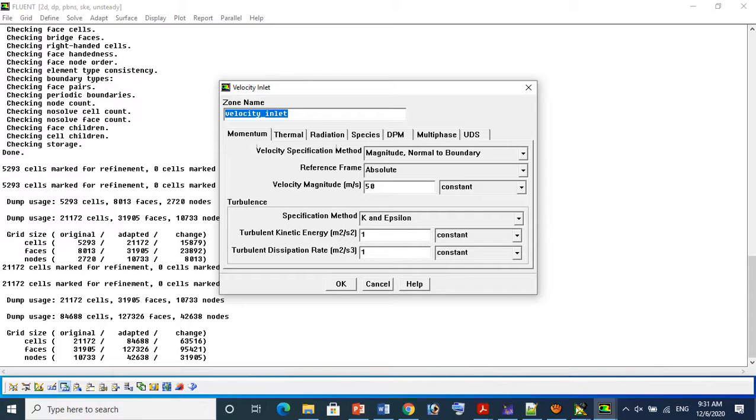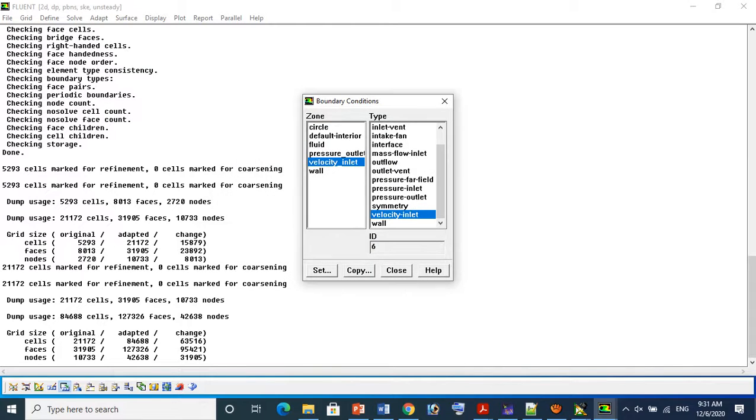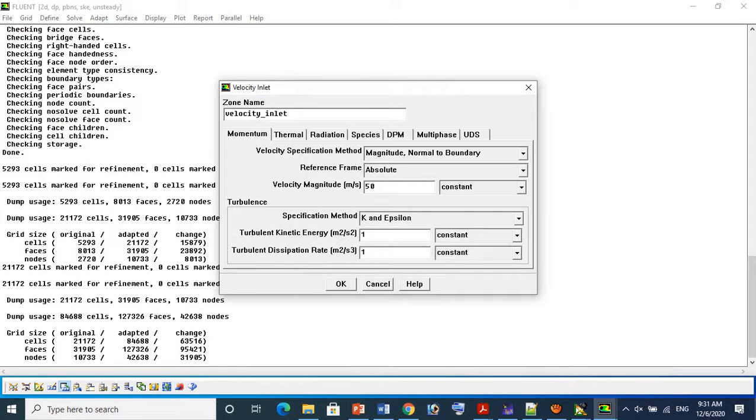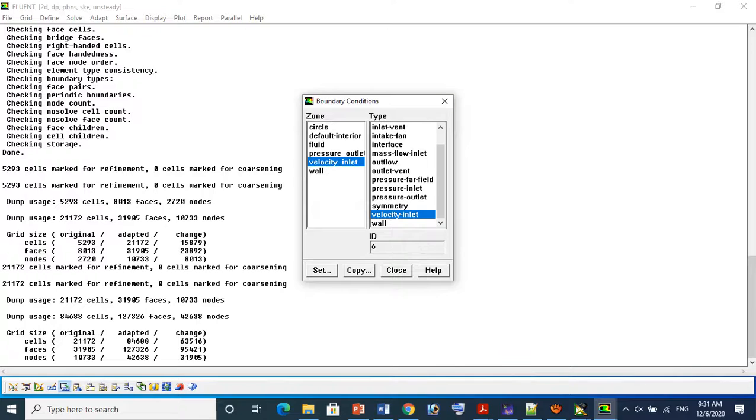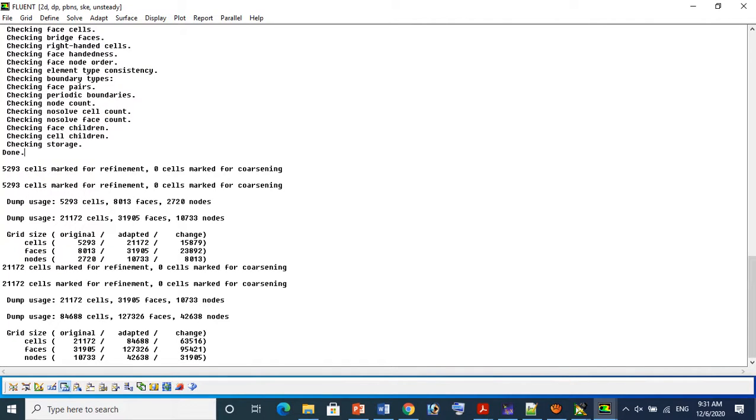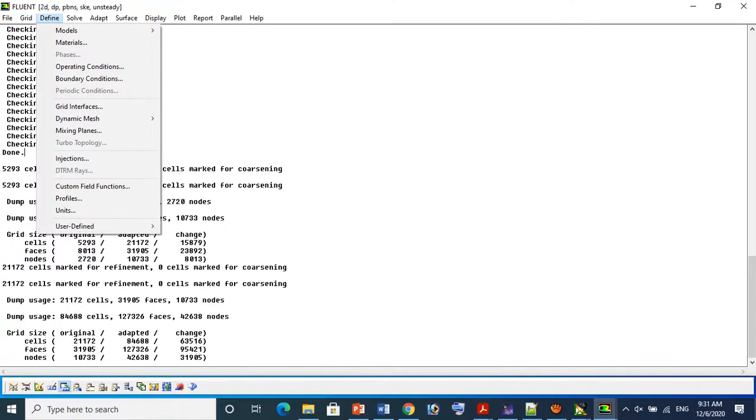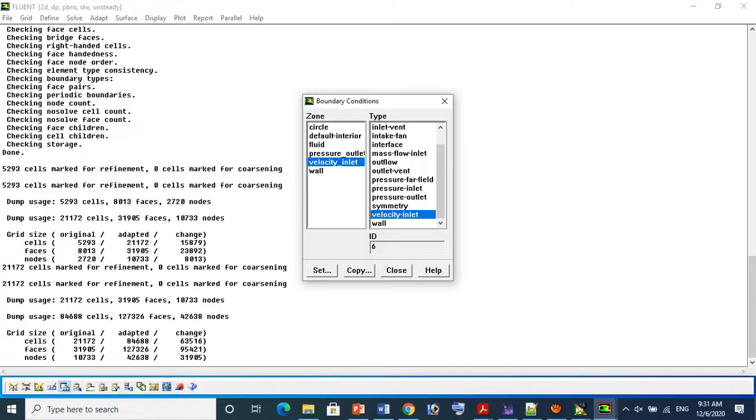So right now we changed the turbulence to the standard K-epsilon model, and the kinetic energy is very low. Here also we have a very low kinetic energy model. Right now we can change it. If you want to do more research over here, you can change this parameter and the turbulence model, and study the effect of turbulence on the flow over the circle cylinder. Right now, for understanding purposes, I am teaching only a small level of pre-processing and post-processing. You need to understand more.